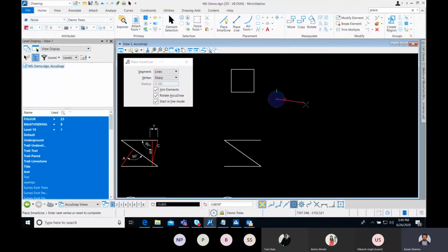The current compass is polar. I can change it by pressing the shortcut key M. See, it has moved to distances x and y below. If I press M again, it will be distance and angles. Okay, so just 2-3 useful shortcuts which I'll try to show you. If anytime you are trying to draw and you want it to be at 90 degrees, just press enter. It will lock to the nearest axis. Okay, and again, I've shown you the shortcut key M already to change the mode.